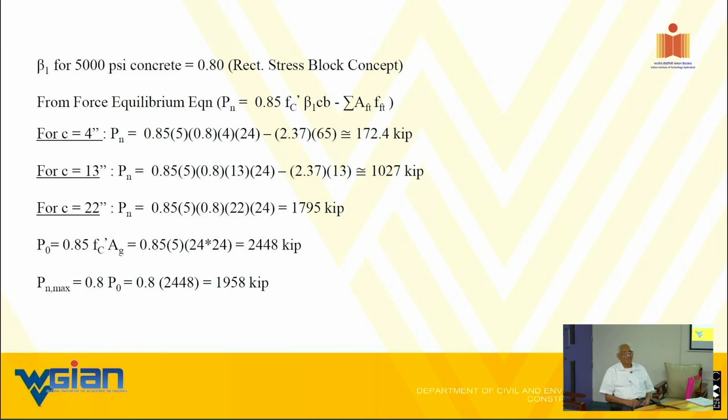You understand. In India, column design, if I consider, we start with 0.4 A_c f_c plus steel. But here it is 0.8 times 0.85. Correct. The 0.447 is also coming because first of all we use the cube strength.